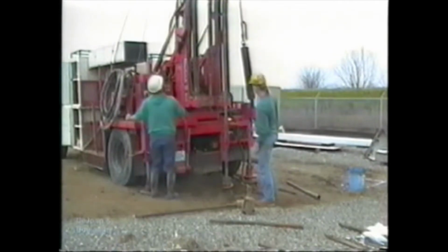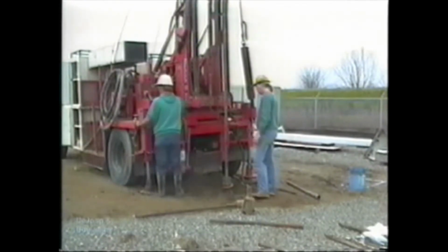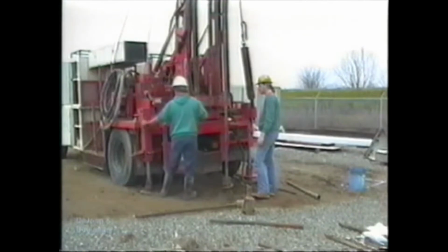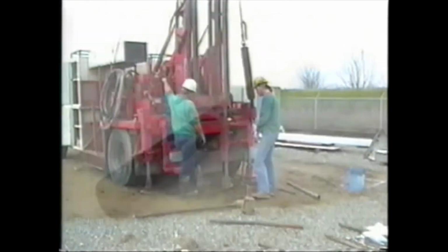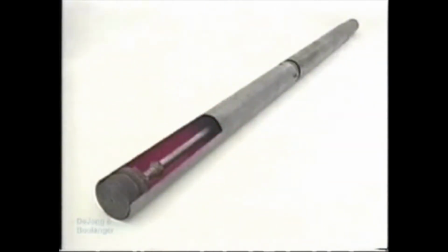These conditions can be greatly improved by using a piston to close the lower end of the tube until the sampler has been firmly positioned against the undisturbed soils at the bottom of the borehole. The piston is then held at this elevation, in contact with the soil, while the tube is advanced around the piston and into the soil. Initially, the presence of the piston prevents soil from rising into the tube faster than the tube's penetration rate.